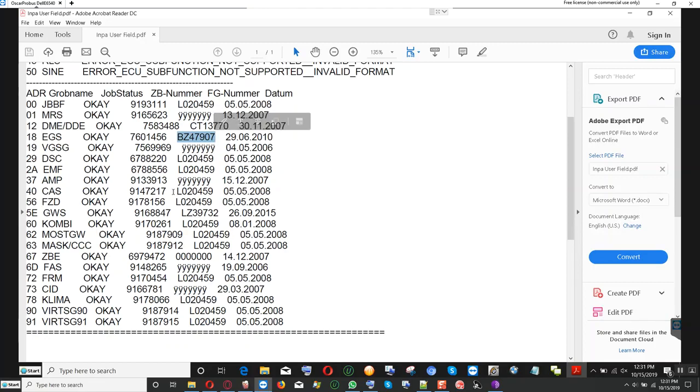Got the CAS unit here. It has the VIN number correct for the car chassis, and also the FRM here. But because of these two things right here, the DME has the wrong VIN and so on, it can't determine what chassis it is. That's a problem here.